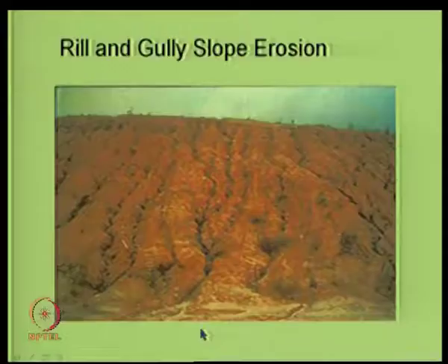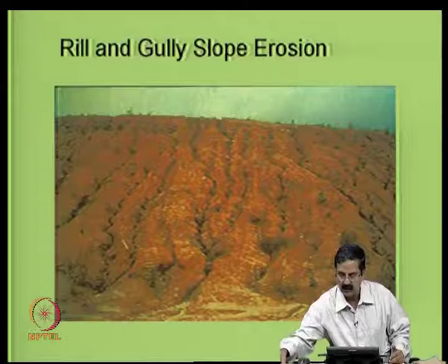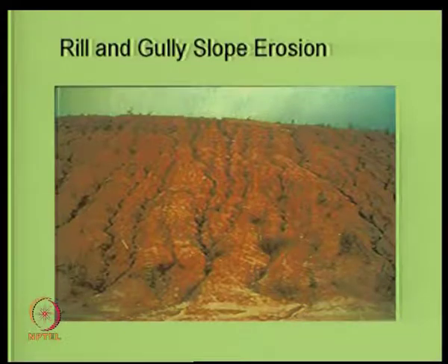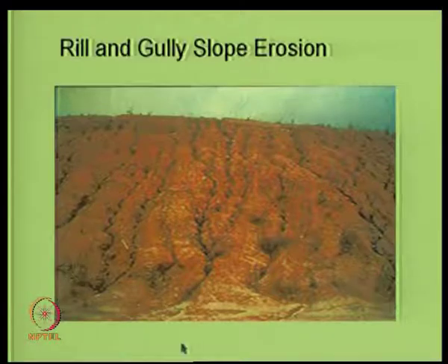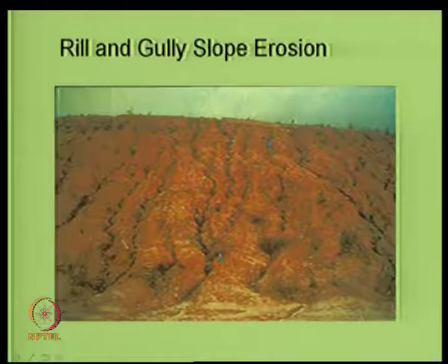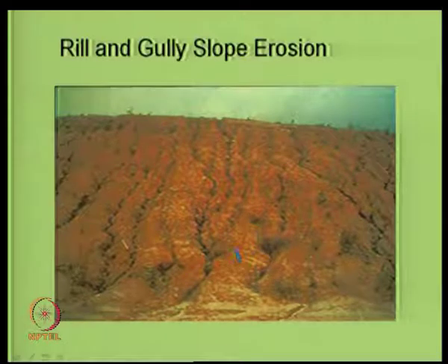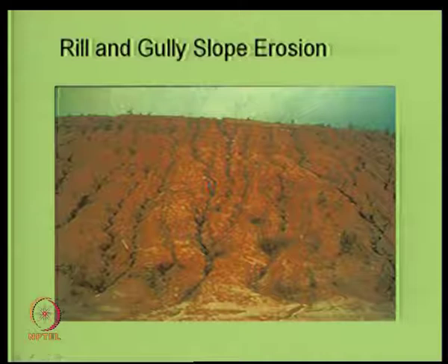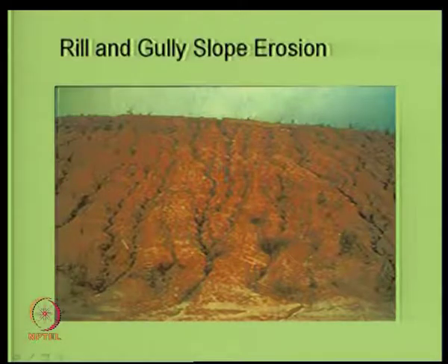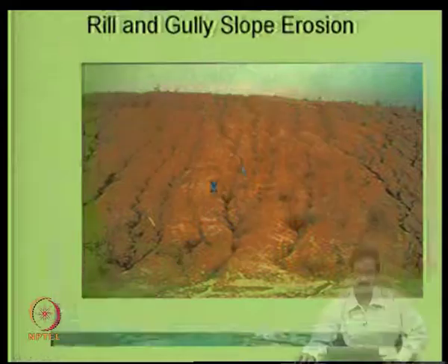So this is a typical diagram of how erosion could be manifested. So for example, we call this rill and gully erosion. These are all quite common in India and many other places. That is because of the rainfall infiltration and the inability of the soil particles to withstand the drag forces. There are drag forces that are exerted onto these soil particles, and they form erosion gullies.